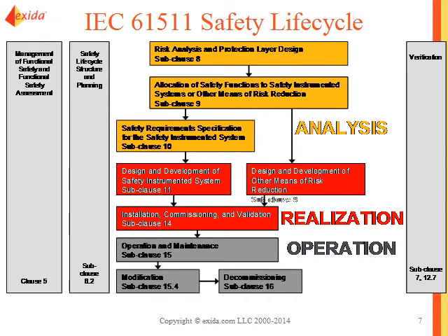So we're going to look at the IEC 61511 safety lifecycle, and most of you are familiar with this. At the top of the slide, we have our risk analysis and protection layer design. We allocate safety functions to safety instrumented systems and other means of risk reduction. Where we have a safety instrumented function, we'll write a safety requirement specification.